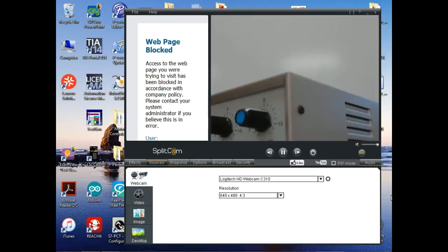And depending on what you wanted the second one to do, the first one would be a normally closed, right? You understand? But your second one would be what you want your timer to do. So we could use multiple timers and get a longer delay, or we could buy a timer that gives us a better option. So you're right; these are 30-second timers.